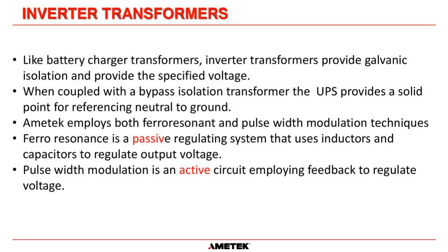SCI builds both ferroresonant and pulse width modulated inverters. Ferroresonance is a passive type regulating transformer, and it accomplishes this with inductors and capacitors. Pulse width modulation is an active circuit employing feedback to regulate output voltage. I'm not going to go into details on this. Craig discussed this in a previous seminar. I just wanted to mention it right here.